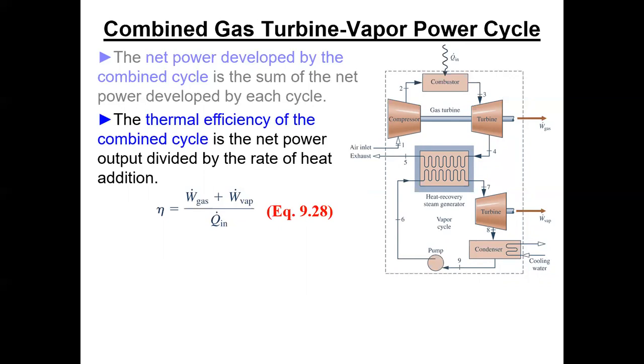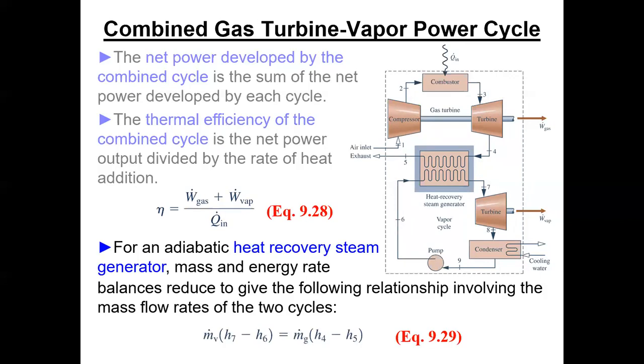Oh yeah, what they do is take those exhaust gases, and there's a heat exchanger called the economizer at the tail end. It takes the water out of the condenser, the makeup water and all that, and that's a stage of feed water heating. That's probably the only stage of feed water heating. Very good question. Okay.